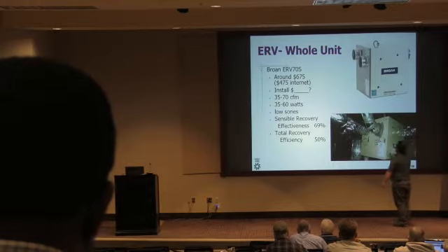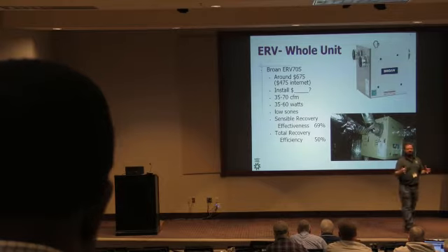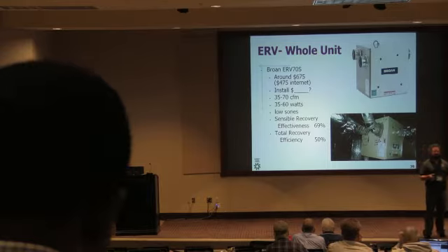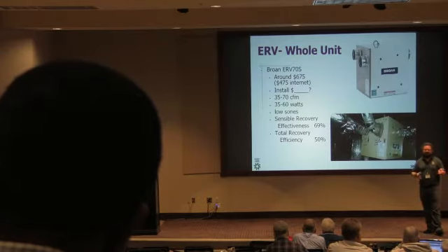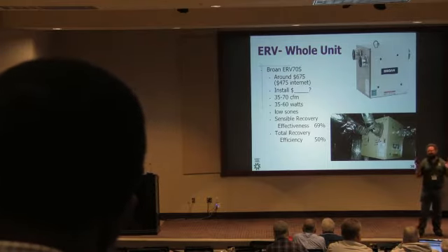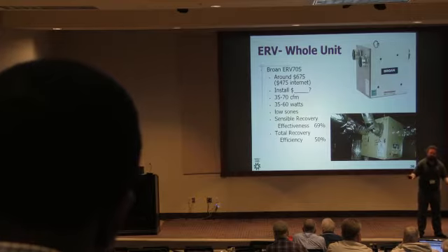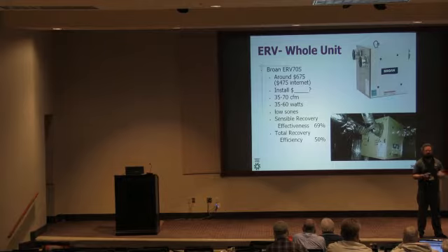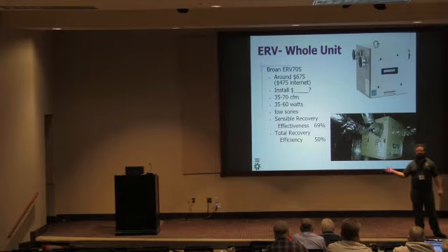This is not the cheapest one that we've seen. Panasonic is actually making a small unit that costs maybe $300 that'll do like 35 or 40 CFM, that might do a small apartment. That's just the cost for the equipment. Someone's going to charge you something to install it, but it's really at a price point where you might be talking $500 or $600 on a small apartment to put in an ERV instead of trying to do that ducted system into the return, or God forbid, a system that just dumps into a closet.